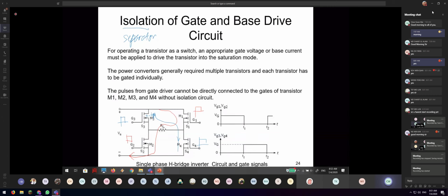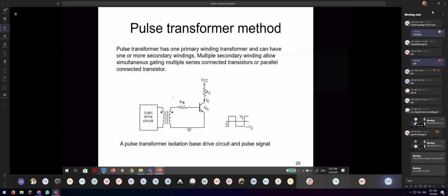Normally in a low power device, no isolation is required. It's okay because normally the power MOSFET or power BJT has high power handling capability, for these 4 pieces. But in a high power motor, the feedback, the transients or the harmonics from the switching on and off of the motor are very, very high. So they need some sort of isolation. So isolation is required, to avoid direct contact between the drive circuit and your high side.